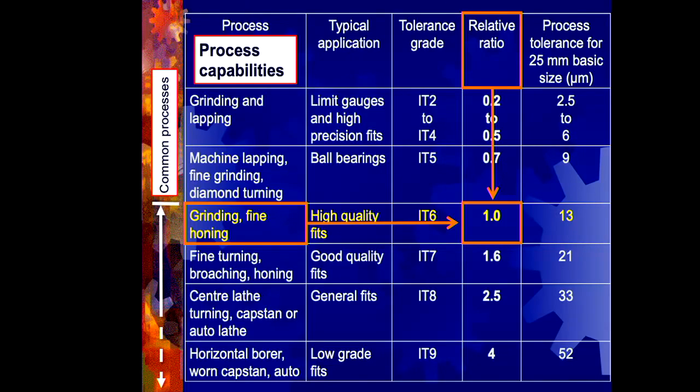When I did lapping, it was a bit of paste, and the guy says it's like toothpaste, but it's got fine, tiny particles of diamond in it. That gets slurped on the plate, which rotates, and then, often with specimens you put under a microscope, you put the specimen on that plate as it rotates, and the diamond, that very fine material, essentially like sandpaper, rubs it away. Because the particulate size is so fine, you've got this beautiful mirror finish, and the surface effect is not part of what you're observing under the microscope. That's the best answer I can offer.